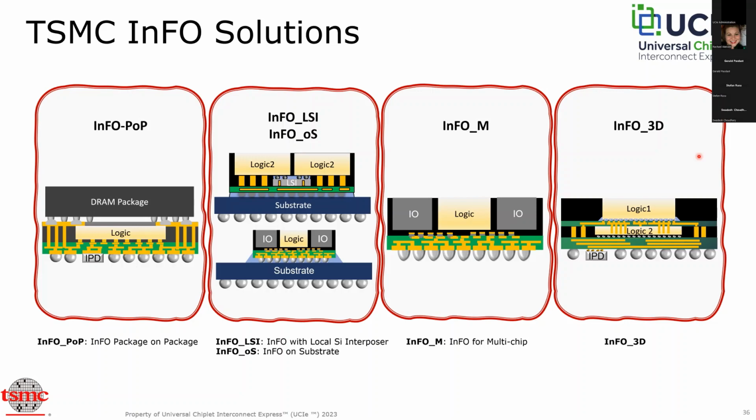The InFO technology envelope has been extended to apply for HPC technologies, including local silicon interconnect, InFO directly on substrate, InFO multi-chip solutions, and 3D implementations.